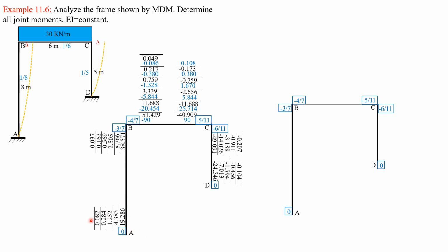Moment AB is 25.305. Moment BA is 50.611. Moment BC is negative 50.611. The calculations and tabulations are correct. You will know that they are correct if these adjacent values are numerically equal. If they are not equal but close, that's still acceptable, but they should be very, very close.